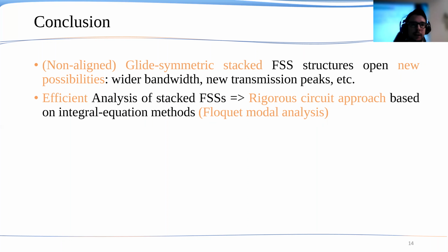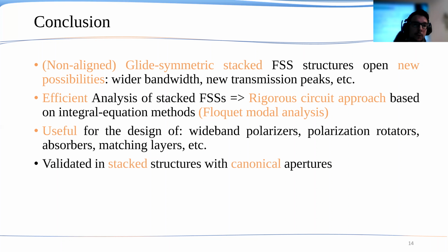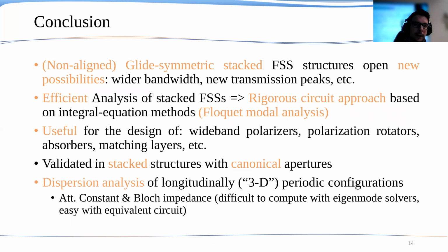For the analysis of this kind of glide-symmetric configurations, we have presented an efficient and rigorous circuit approach based on Floquet modal expansions. We have seen that it is quite useful for the design of wideband polarization rotators, absorbers, matching layers, and other microwave devices. We have validated numerically these results by analyzing different stacked structures with canonical apertures, in this case with rectangular and annular apertures, and we have also plotted the dispersion properties of longitudinally, that is three-dimensional, periodic configurations.